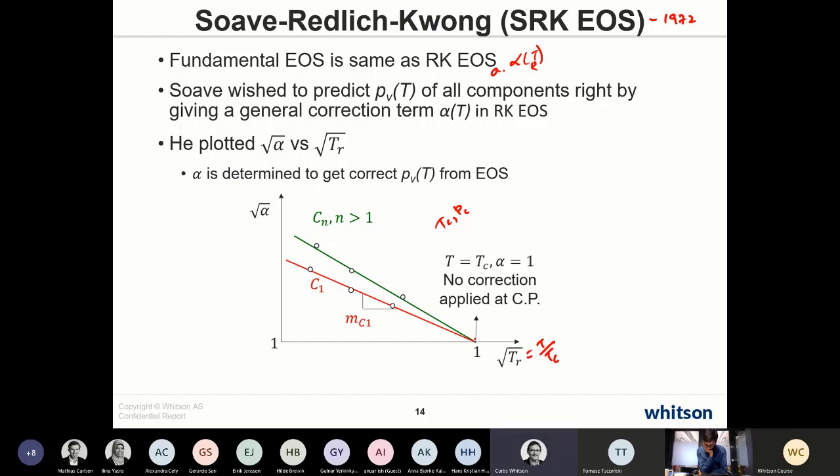And what he used was the vapor pressure that was known experimentally for so many compounds at 0.7, 70% of the critical temperature. The reason that vapor pressure was known for a large number of compounds is because there was a guy named Pitzer who had introduced the so-called acentric factor as a term to quantify the shape of the vapor pressure curve.